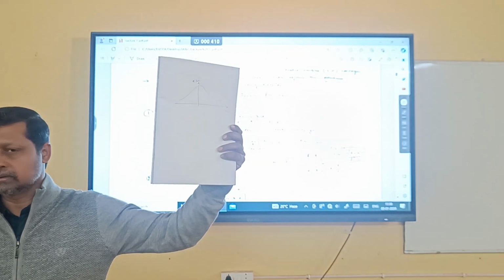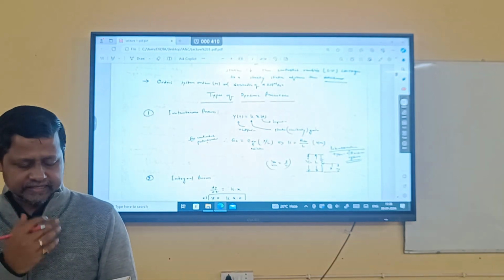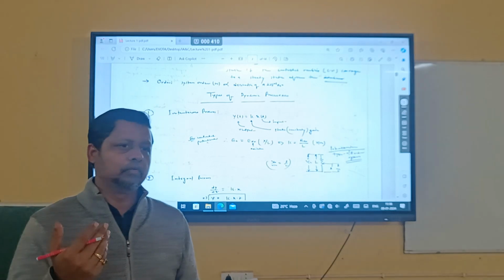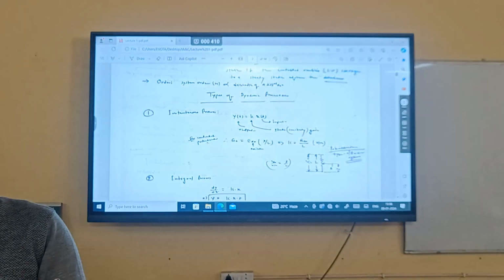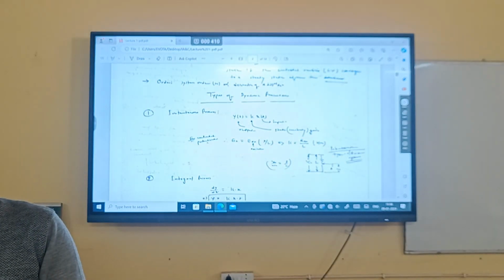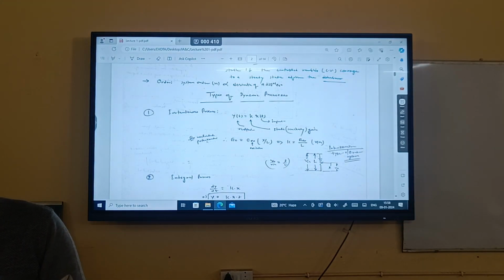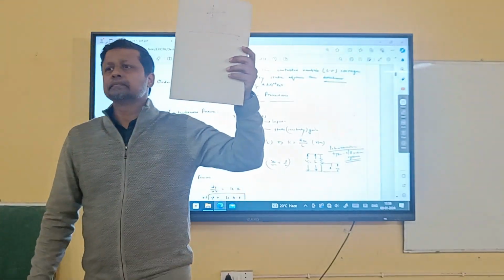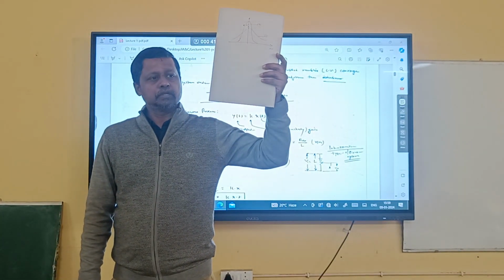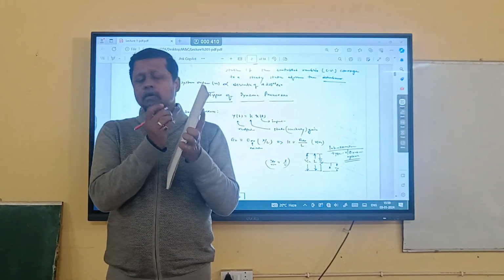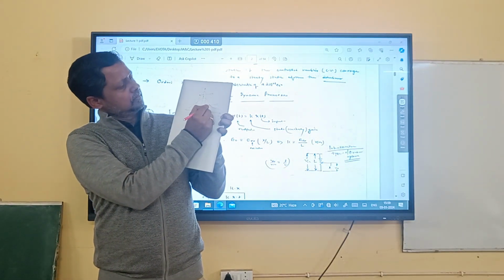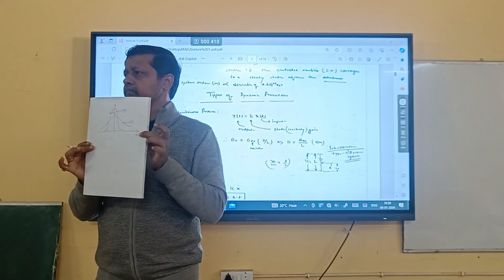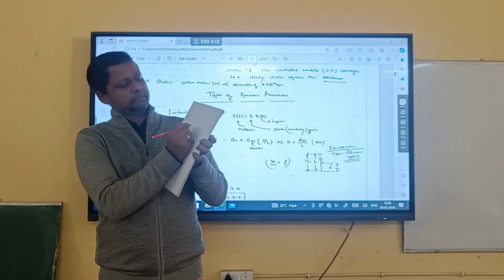Let's say we have done something. We change the element values of RLC, and because of that, next time this curve has been modified like this. Earlier is 1, here I am naming 2. Can you see the clear difference in 2? Refer to curve 1. Can I identify the plus minus 3 dB point? Let's say somewhere here, as an example. So it is plus 3 dB, it is minus 3 dB.